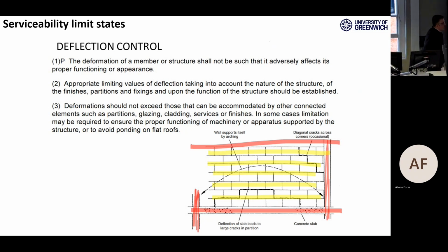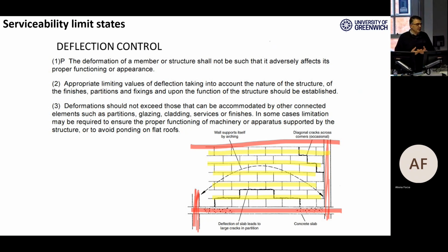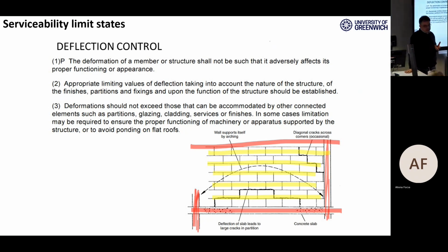We practically covered the crack criteria by a kind of simple restraints on the reinforcement diameter and spacing. So if you put those criteria on the reinforcement diameter and spacing, you will be fine in terms of cracking criteria.